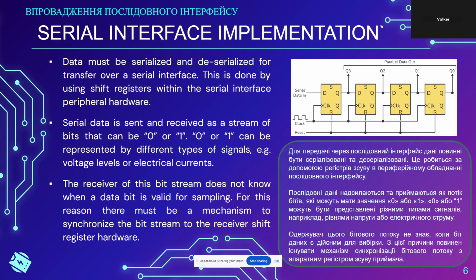Of course, for microprocessors, the voltage levels tend to be going lower, simply because the lower the voltage, the less waste power dissipation we're getting in full high-speed microprocessors. In microcontrollers, generally we try staying at around, at the moment, about 3.3 volts, which is the supply voltage for most modern microcontrollers.